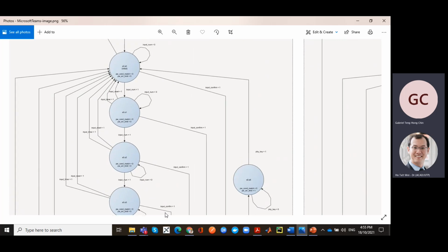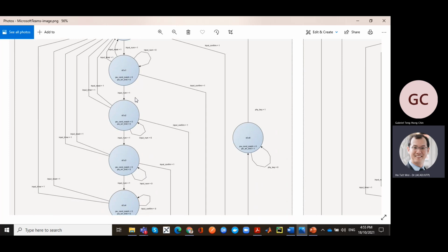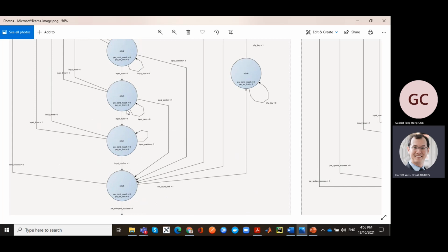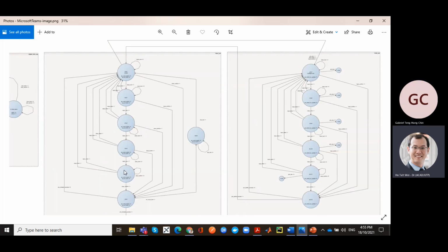Okay, so here there's probably a point of confusion. Maybe what you're thinking about is the number of tries. Say I put a 5 key password wrong, then I put it again wrong, then again. The third time you want to freeze it, right? That's not reflected here. The error key limit here just says after I put in the 5th one, if I put in a 6th button, straight away I'll freeze it. So you're not capturing here the repeated 3 times to lock it.